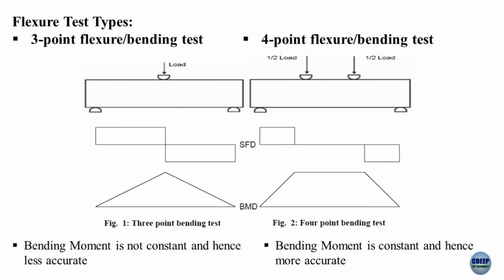A flexure test produces tensile stress on the convex side of the specimen and compressive stress on the concave side. This creates an area of shear stress along the midline. We want to ensure that in our 3-point bending test, the primary failure comes from tension or compression, and therefore the shear stress needs to be minimized. This is done by controlling the span to depth ratio. The span is the length between the supports. The outer span divided by the depth of the specimen should be around 16 for metals, and some other materials require values greater than 16 so that the shear stress is low enough. For our test today, we are going to use a 3-point bending test setup.